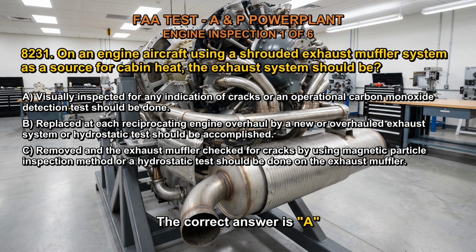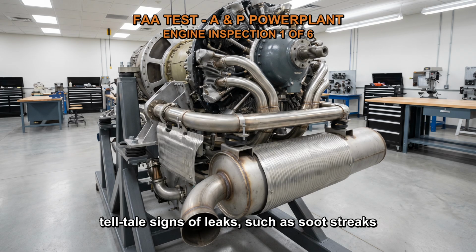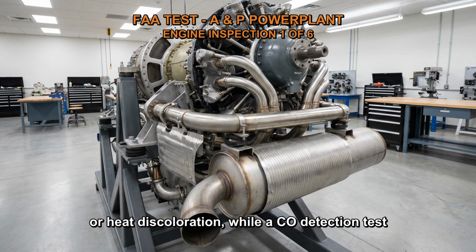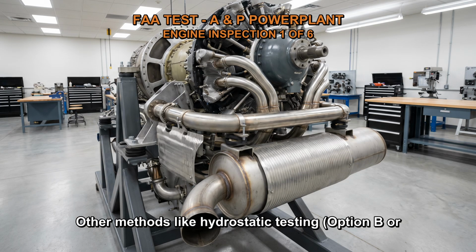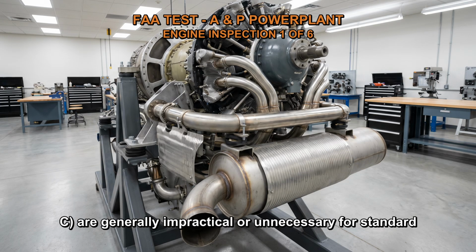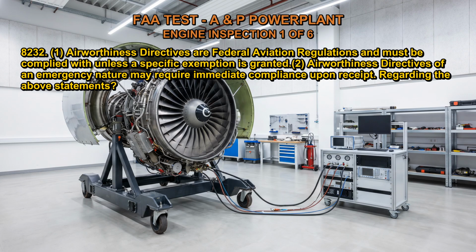The correct answer is A. A visual inspection allows technicians to look for telltale signs of leaks, such as soot streaks or heat discoloration, while a CO detection test provides a definitive check for toxic gases that may not be visible to the naked eye. Other methods like hydrostatic testing, option B or C, are generally impractical or unnecessary for standard exhaust maintenance compared to these direct safety checks.